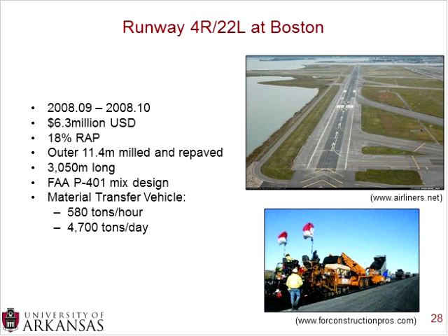And this project was approximately 3 kilometers long. It used the FAA P401 mix design, and this is a really nice example of using this new technology and using existing specifications. And I think that as we learn more about warm mix asphalt, we will be able to maybe make some recommendations on those specifications, but we are getting projects completed using existing specifications.